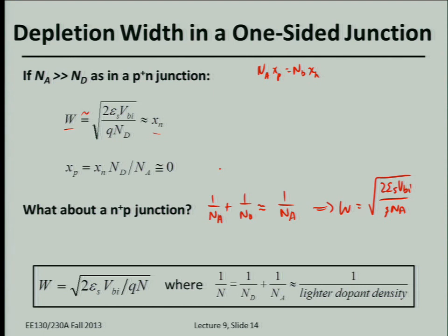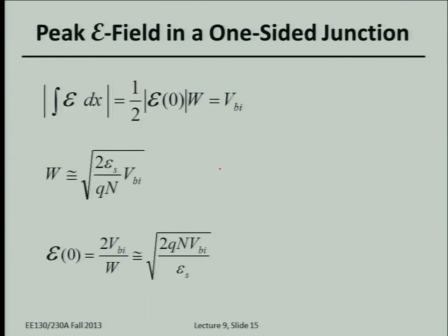The depletion width can change over more than one order of magnitude, but typically it's on the order of a tenth of a micron. So anywhere from many tens of nanometers to hundreds of nanometers. So it's usually less than a micron. Now if you have a photodetector, then you might purposely make it more than a micron. But for order of magnitude, when you're doing your homework, if you're getting a centimeter or something, the answer is way off.